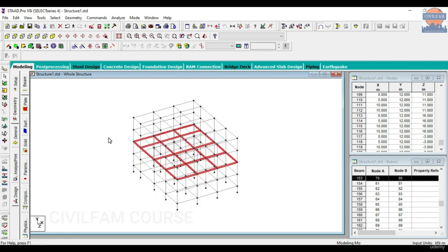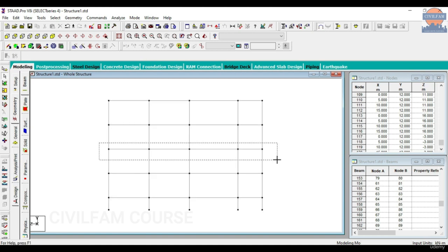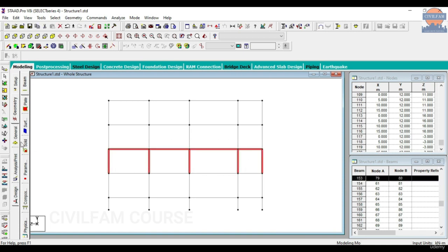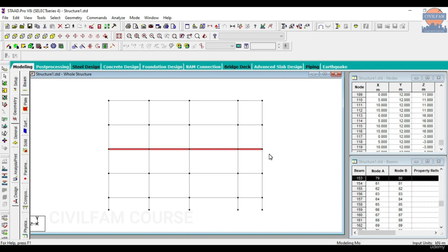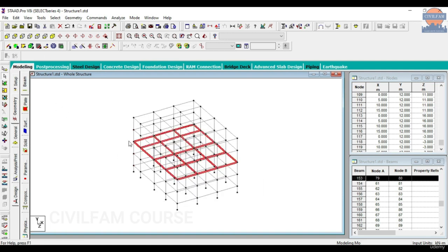Now the question arises, if you just want to see this level. For example, I have got some extra loads coming on it, or maybe I'm deleting some beams from here. What I can do is view that particular floor. Just select this entire thing. Maybe I want to see only this floor, and again make a note that you shouldn't come like this, because even the beams will get selected. You have to be in the upper half and set it like this. Then I come to my isometric view and I'm able to see my floor level. Now I want to see only that particular floor.